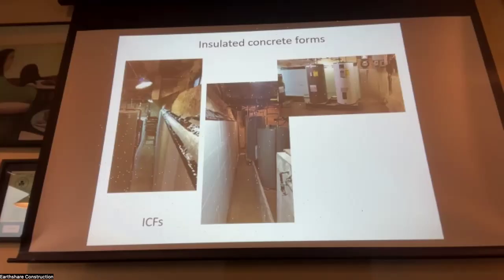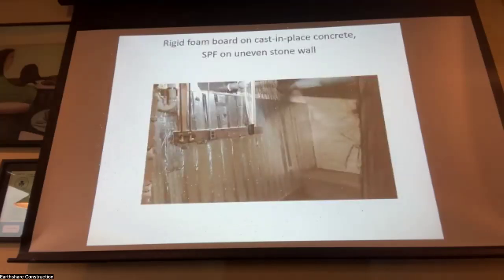Yeah, high variability. In Vermont, rubble stone foundations are a lot of shale type small stones. I have some big flat stones, but behind it's all small rubble. On this side of the river, you might have car size chunks of granite. Those aren't going anywhere. They're not gonna move. So the foundations are very different depending on what they're made out of. So which one would you rather plaster or spray? Not with the granite.